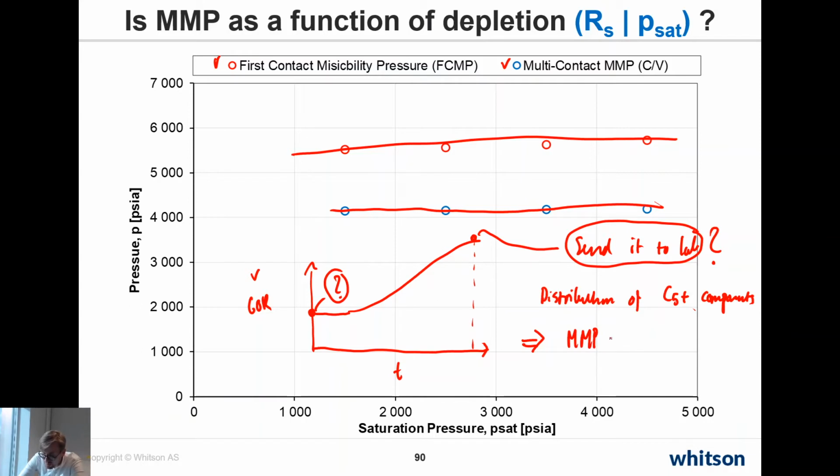correlation, that MMP correlation is typically correlated to either C30+ over C5+, or maybe the inverse of that, depending on which correlation, I guess. But this distribution of the components that are lighter than C30 versus the components that are C30 and heavier essentially can be used to generate almost like a straight line in terms of MMP, if you plot the MMP by different mechanisms versus the C30+.